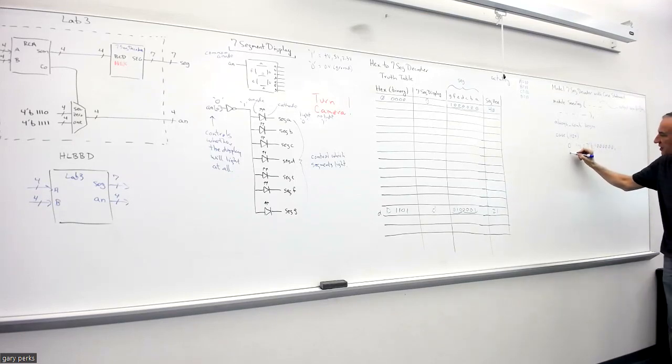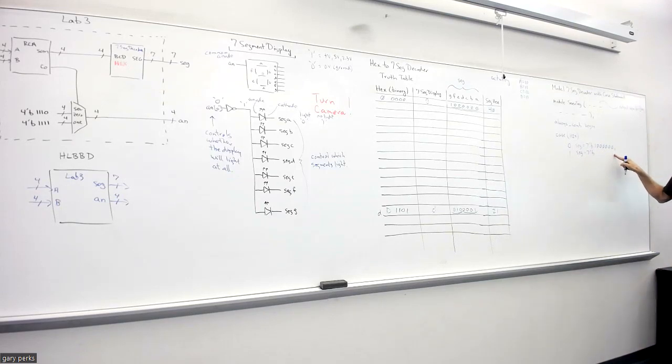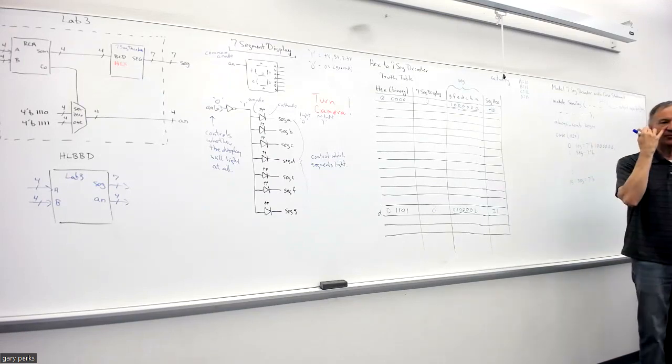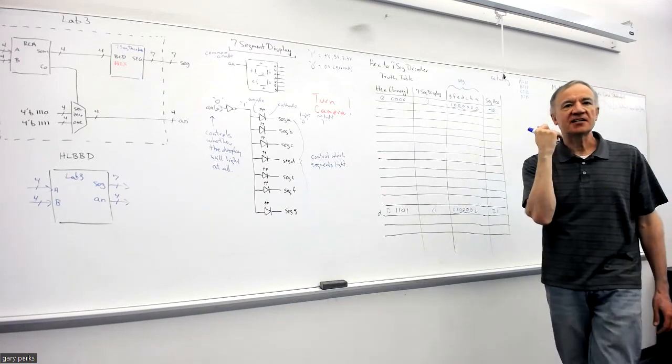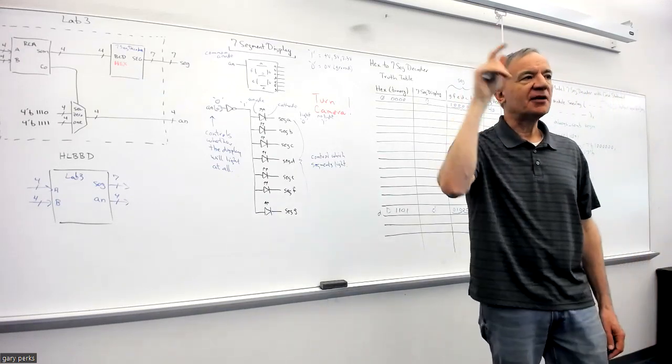And then you would do, you know, like 1, right? Seg 7, tick mark B, and then you'd have to put the 7 bits in order to light up a 1. Okay, and then you would just keep going. Eventually you'll get to 15. Right, so again, you'd have seg equals 7, tick mark B, and you'd have to put the bits that you need in order to light up. Well, what do you want to light up when you have a 15? What's 15 in hex? Yeah, so capital F.